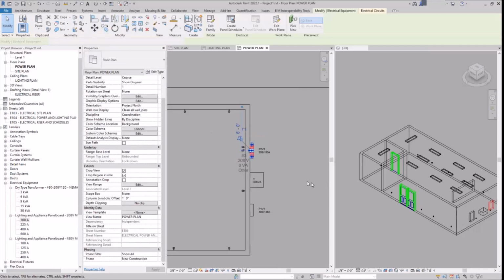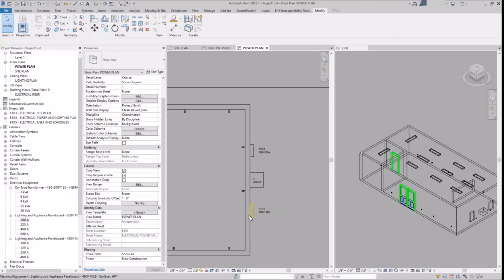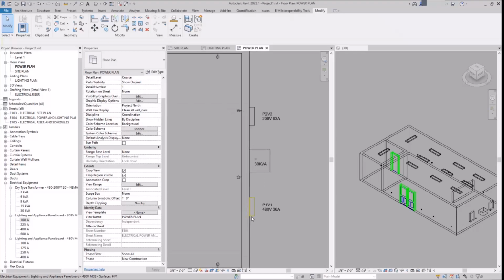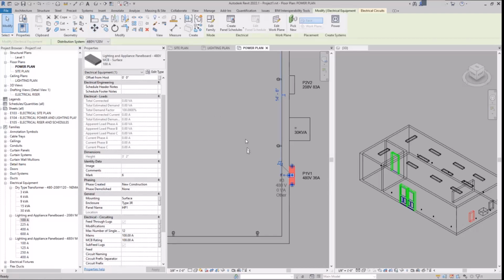You did mention that this specific client wanted the 480/277, right? That is correct. Yeah. They want to be able to power everything at 480 volt. So that's why we're setting a 480 volt panel running circuits, lighting circuits. They've also got a welder and a couple other things, which we're not going to get into. We're not going to show it here, but there will ultimately be additional things on this 480 volt panel. That's why it's a panel instead of just a disconnect. So we name that. Got the distribution. Okay.